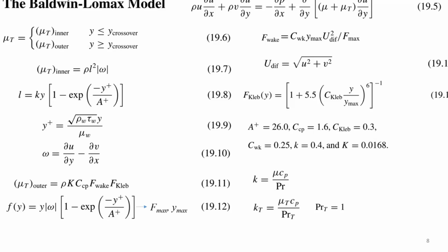The idea is the following: we will try to present the presence of turbulence, or this high energy exchange between the boundary layer and external flow, as an increase of viscosity. With an increase of local viscosity, we will model exchange of momentum and exchange of energy.